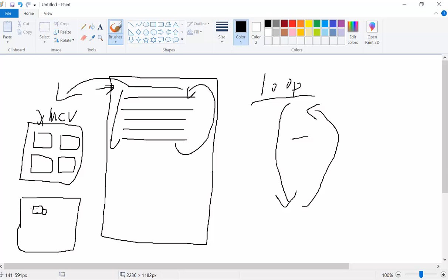So here's the difference. The FPGA chip only has general purpose gates floating there, and your program will rewire everything and make a specific digital block. But for the microcontroller, everything is there already. It's just taking different instructions to let the MCU know what to do for the next step.